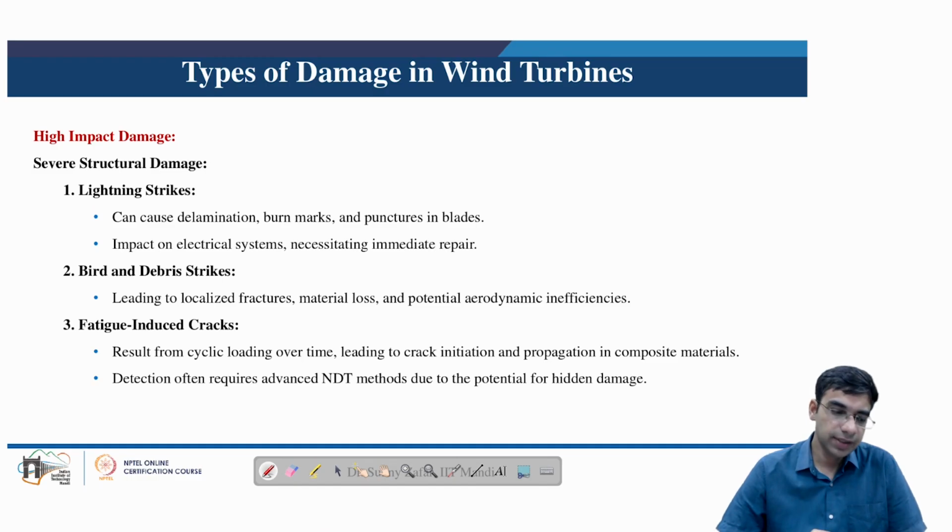Bird and debris strikes can lead to localized fractures, material loss, and potential aerodynamic inefficiencies. Fatigue induced cracks can result from cyclic loading over time, leading to crack initiation and propagation in composite materials. The detection often requires the use of advanced non-destructive testing methods due to the potential of being hidden damage.